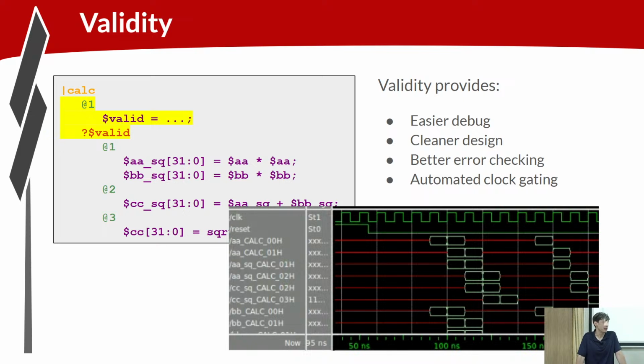Yeah, I mean that's one use of this knowledge, to generate your clock gating logic. And the valid is the enable for the clock. How do I verify that the enable is not generating a spurious edge on the clock?